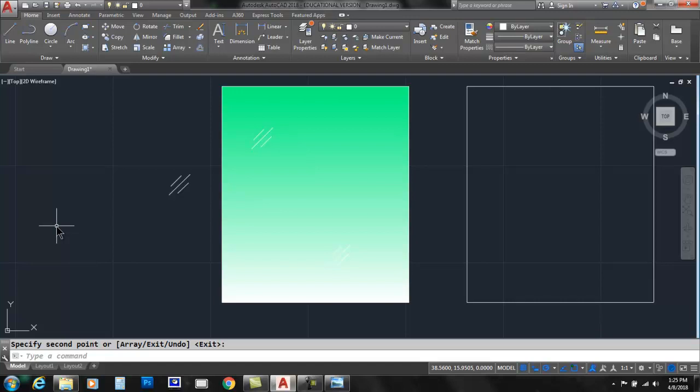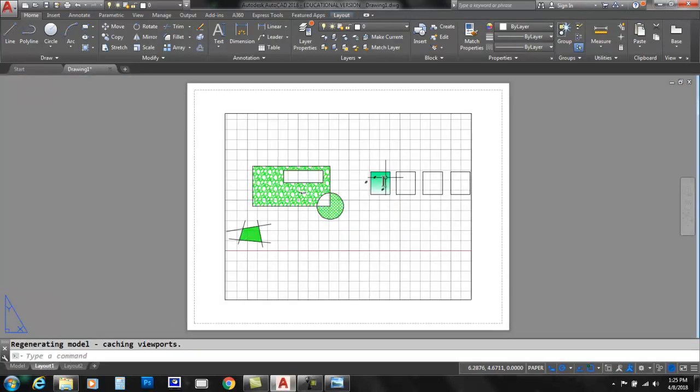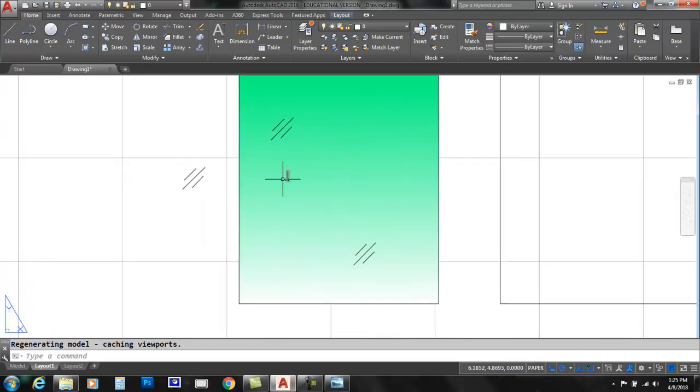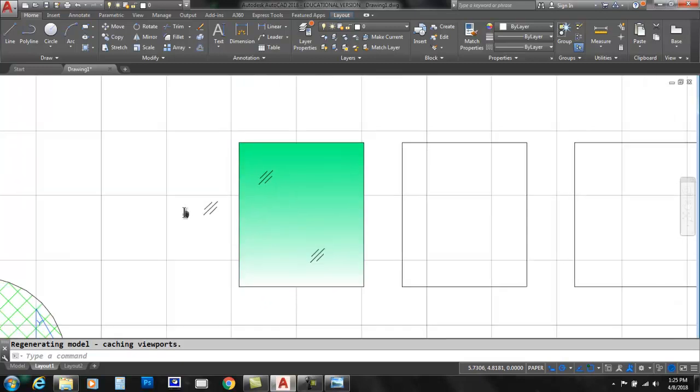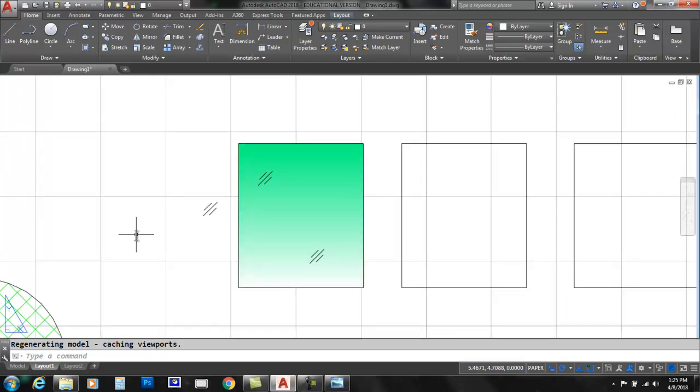that you don't think about at this stage. I'm going to select my Layout 1 tab, and then when I zoom in, you're not realizing that white is really black on a piece of paper, so those glass lines are very evident. Okay, and that's a little mini lesson right there, is that whenever you're adding solid hatching or even line hatching, like the ANSI 31, with different colors, always jump into layout space to see what it actually looks like on a white background, which would be your paper.